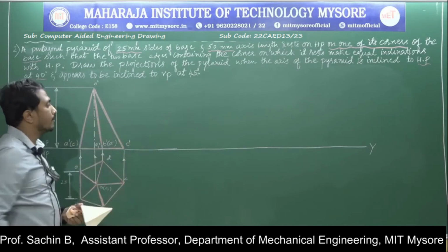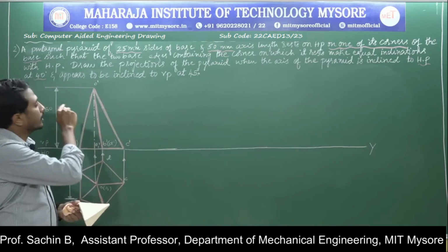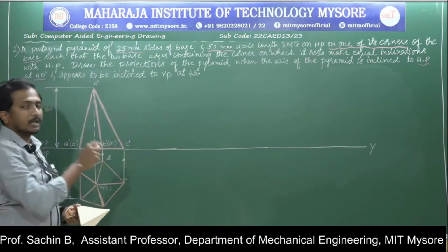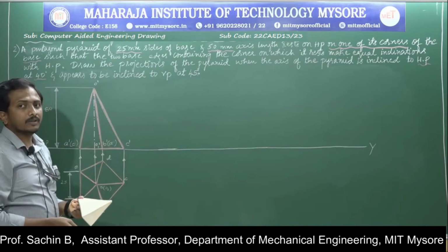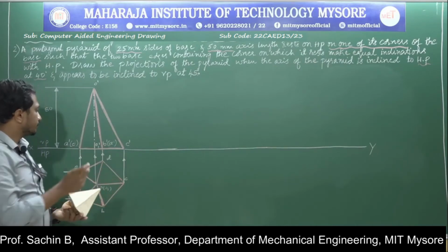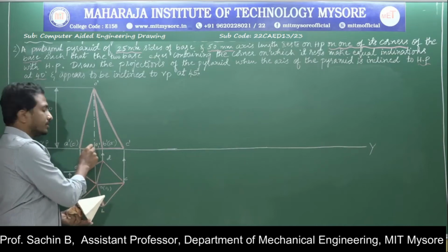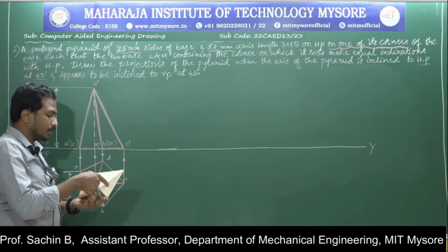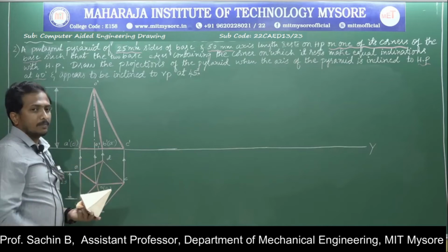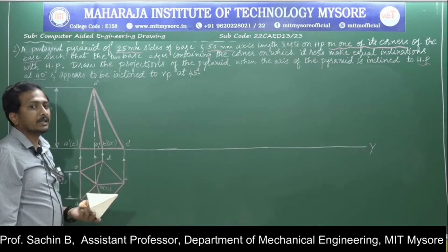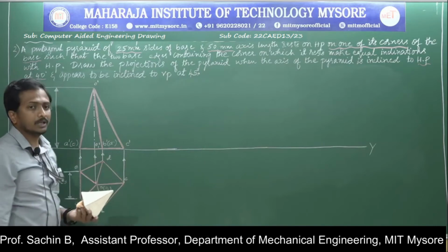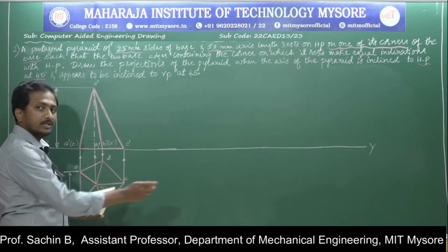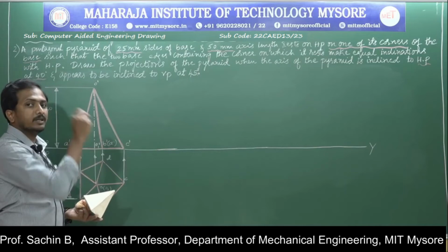Now, with reference to the axis, it is very difficult to construct the axis inclination by drawing an axis length of 50 mm and making the given angle. To overcome this issue, as explained in the last problem, this axis is inclined at an angle of 90 degrees with the base. By knowing that, we subtract the given angle from 90 degrees. That is 90 minus 40 degrees, which gives a 50 degree inclination. With that 50 degree inclination, we will construct the base first, then the axis.